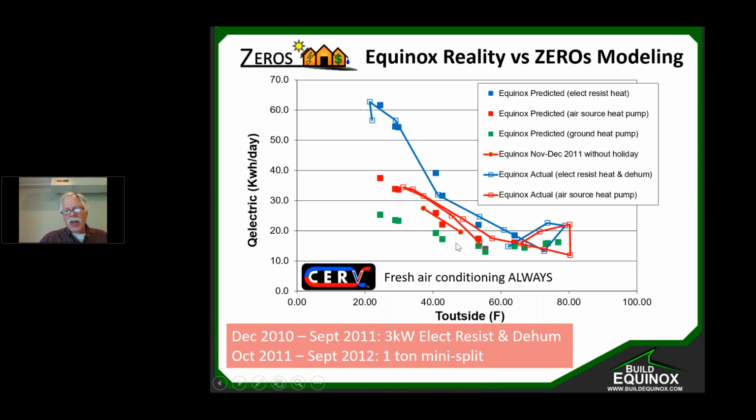And if we had, say, an even higher efficiency coefficient of performance of about 4, rather than about 2 as I use for the mini-split heat pump, something like a geothermal or today's generation of mini-split heat pumps, that would be the kind of energy gain, in kilowatt hours per day, we would expect versus outdoor air temperature.